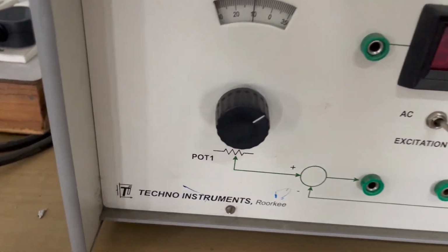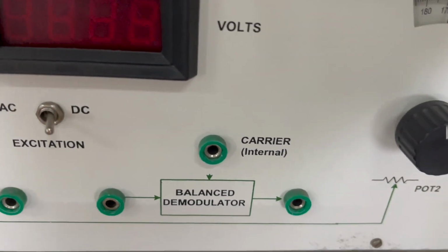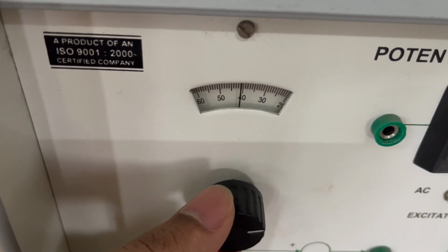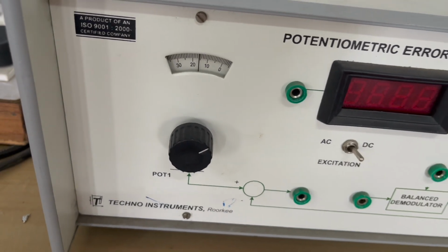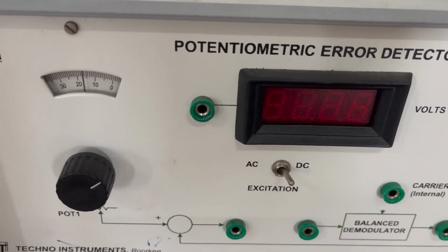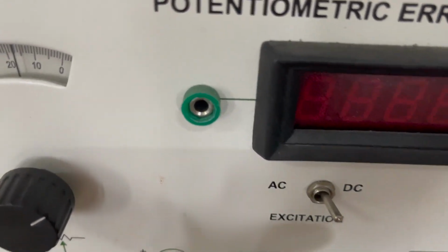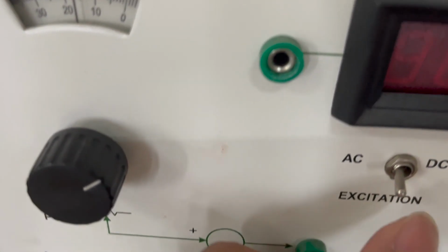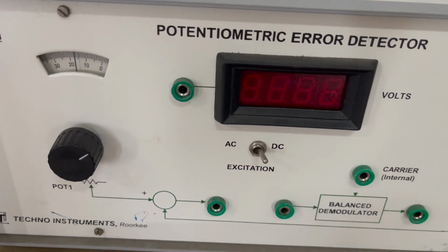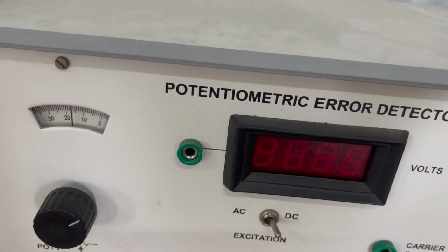As you can see here, there are two potentiometers, part 1 and part 2, the resistance of which can be changed by rotating this knob like this. And this experiment can be performed both for AC excitation as well as DC excitation, and we can change the excitation with the help of this switch. Also there is a voltmeter display which basically shows the voltage corresponding to the angular position error,